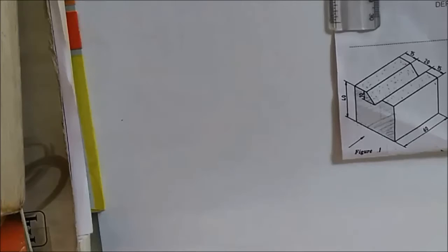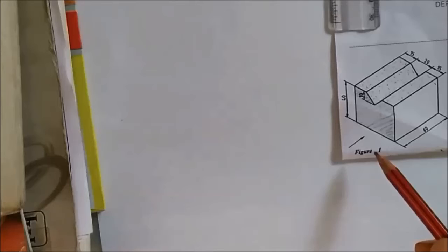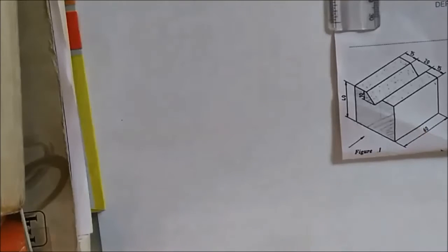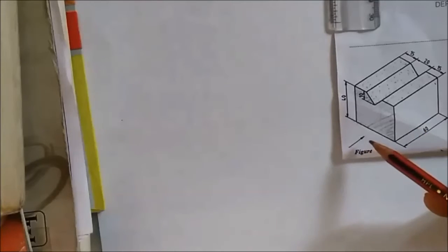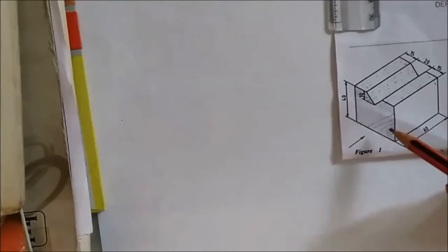Now start figure number 1. We have to draw the orthographic projection of this drawing. See, there is an arrowhead. This arrowhead indicates that this is the front surface of this object. So we have to visualize the object from this side for the front view,